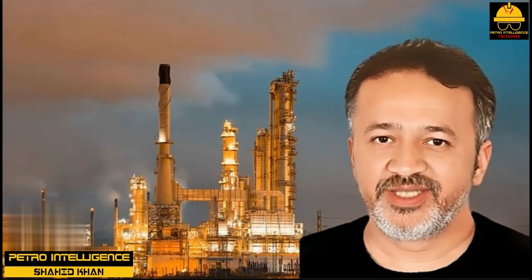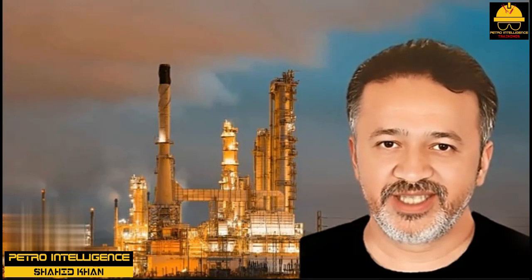Selecting an optimum tower pressure. The process design engineer selects the tower design operating pressure as follows. 1. Determines the maximum cooling water or ambient air temperature that is typically expected on a hot summer day in the locale where the plant is to be built. 2. Calculates the condenser outlet, or reflux drum temperature, that would result from the above water or air temperature.